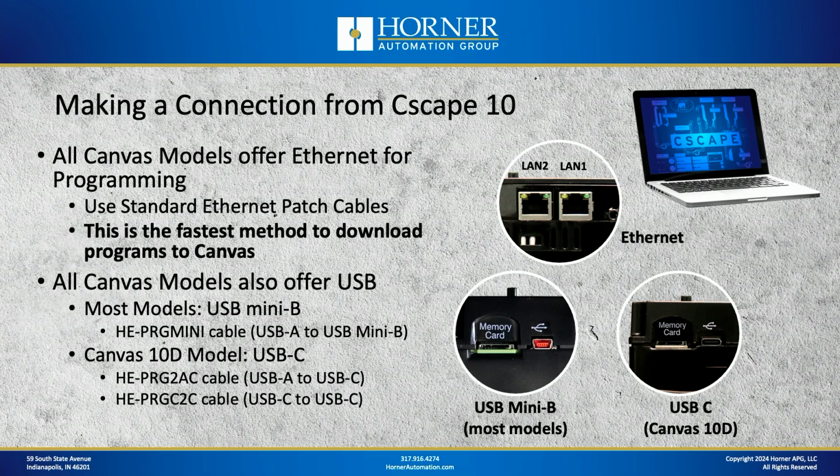Now, when it comes to the physical connection between your computer and Canvas, like the Micro OCS, you have a couple different options. But with Canvas, we really recommend that you utilize Ethernet as your connectivity from your computer to Canvas. Why are we recommending that? Well, that's because we can more quickly download larger files over Ethernet, so the downloads don't take as long if you perform those over Ethernet versus performing them over USB. So that's the recommended connectivity for Canvas, at least the most recommended.